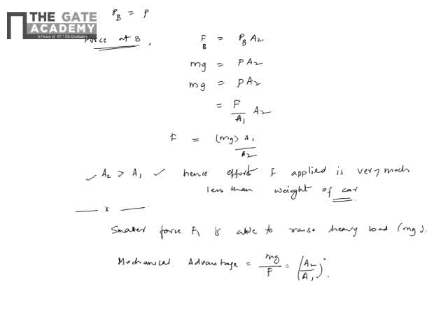But remember that the work done by F will be the same. I mean, the work that is done by F will be all utilized. Work done will be the same. The only difference is in the effort that is applied to raise the load. So this is the working principle of the hydraulic lift.